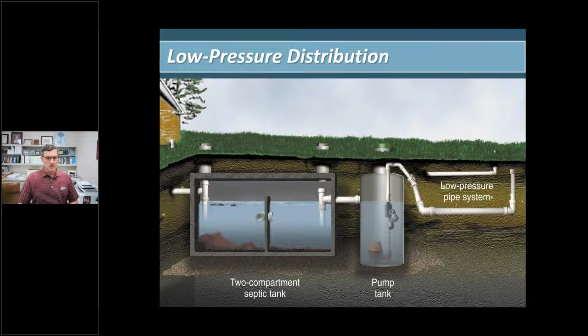All right, dealing with different soil types that may be less conducive for absorption, you will start to see some spray heads or some movement of that liquid out. So this pump tank here operates almost exactly as wastewater lift stations do, which may be in communities or towns, where you're having to physically move wastewater from one area to another, ultimately moving it to the treatment plant.